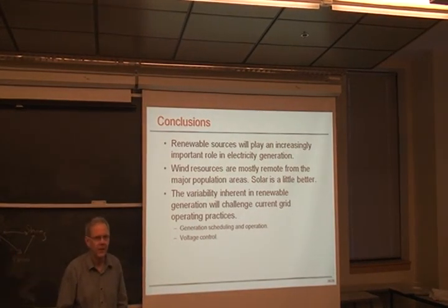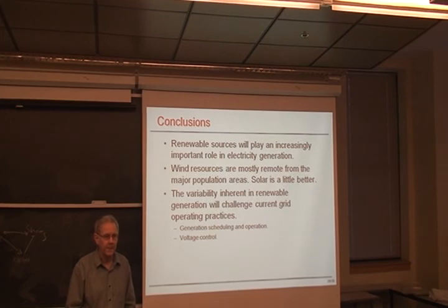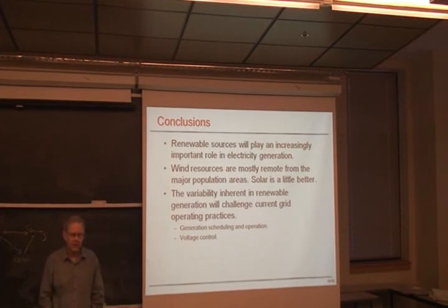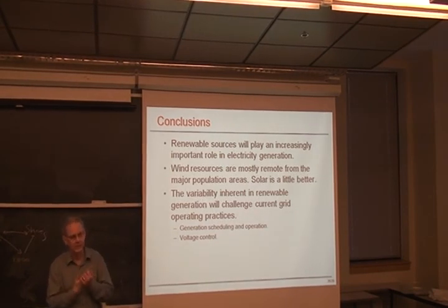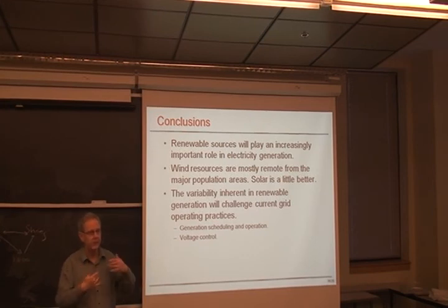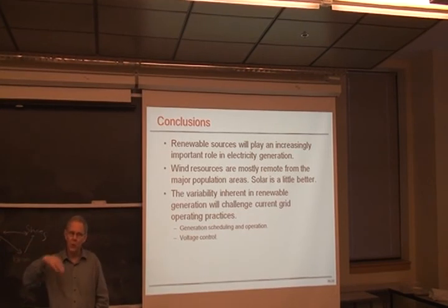How easy is it to curtail wind and solar? How fast can it be done? If you want to do it for economic reasons, to reduce, for example, the variance, is it done easily? So it can be done quite quickly. In the case of wind, it can be done in a one-way direction. If you want to curtail, it's easy. You can just spill wind by rotating the blades, increasing the pitch angle, and that makes the blades less aerodynamically efficient, so you lose mechanical torque and you lose electrical torque. So you have a one-way control: you can drop power fast, but you can't increase power.